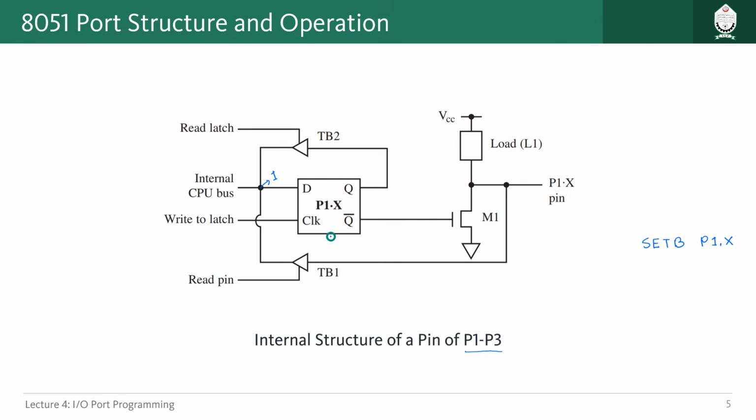This one is just a D latch. Whatever you give through this line, 1 or 0, if you enable the latch, which is level triggered, then with a pulse like this, 0 and 1, whenever you have 1 at the enable, whatever you have at D will be latched onto Q and stored in our D latch.